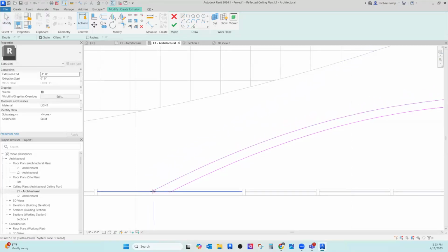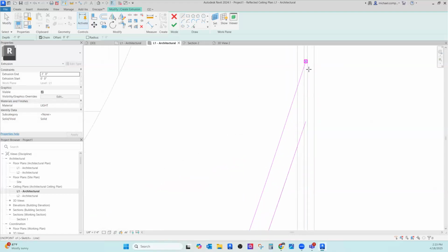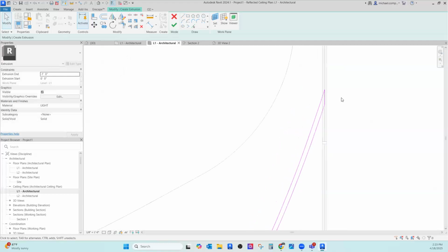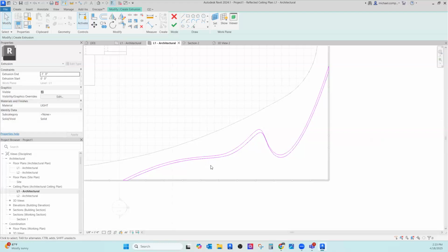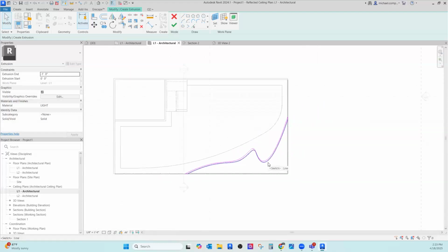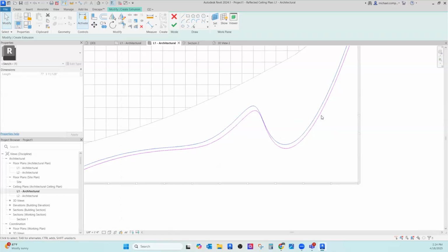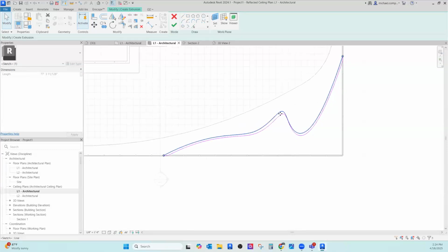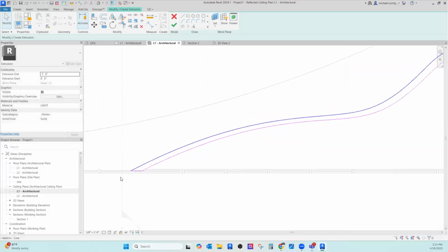And then what I'm going to do is close up that geometry, because it has to be a closed polygon, remember? And I can tweak these things later, but I'm just trying to get this right. All right, so make sure these lines don't cross, they don't. So there's my light. And the exterior of that light is going to follow the line of the architecture. The interior line is going to be slightly different, but similar. And if I really wanted to tweak it, I can play with it and manipulate the geometry, but I'm just going to leave it for right now. Hit OK. What does it not like? Something's intersecting it doesn't like.